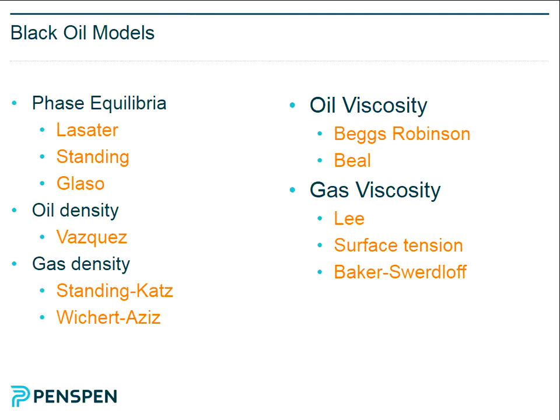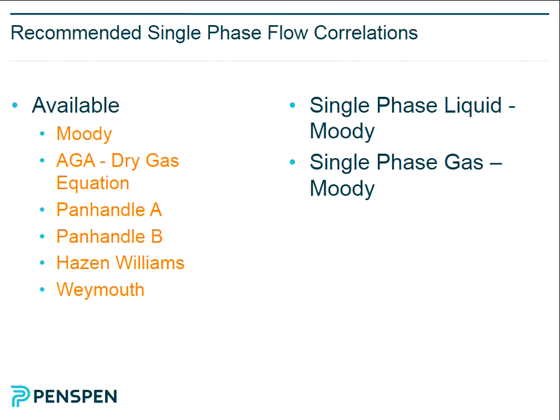And there's applicability as well for various flow correlations. This is actual single phase. We see Moody applicable for everything. That's the chart, so you may as well use that. It's easy. And then you don't need to remember this. The principle is you've got different circumstances, and different researchers' work is applicable to different circumstances.